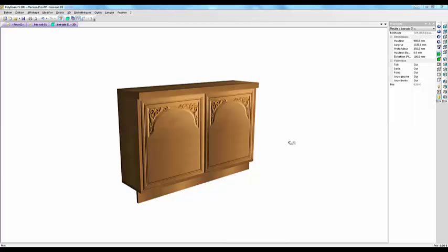Of course, these decorative effects are not machinable from the Polyboard file. You'll have to add these decorative effects to your machine code if you're using a CNC, and they do not in any way affect the structure of the panel. But it's a very good presentation tool if you need to model and show somebody, or show yourself, what different styles of paneling can do for a design.